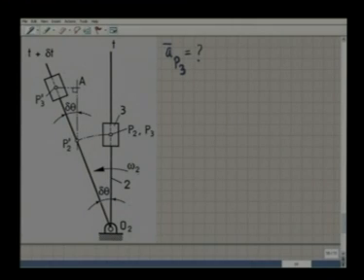Because the observer is always sitting on body 2, he or she thinks that P3 is moving only along the rod. No motion perpendicular to the rod of P3 prime is perceived by that observer. So, what he or she misses is this transverse distance. According to the observer sitting on body 2, the transverse displacement is only this much. But as we see from the figure, the transverse displacement is this plus this. It is this plus P3 prime which the observer misses.